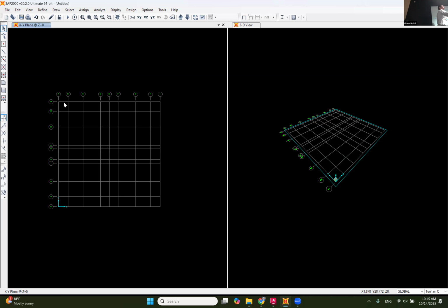So basically, once you have the slab system, let's say this is 5 meter by 5 meter, and you make the mesh size of the slab one mesh. So basically, the finite element is going to solve for 0 deflection at the supports, and the deflection that you are going to get in the middle is going to be 0.